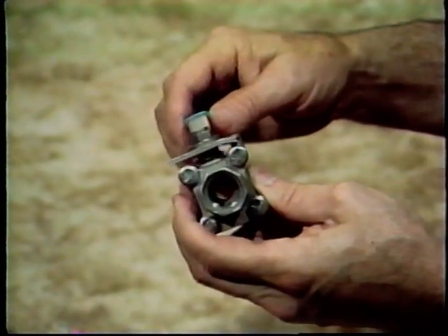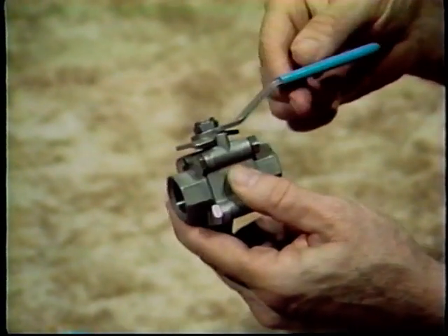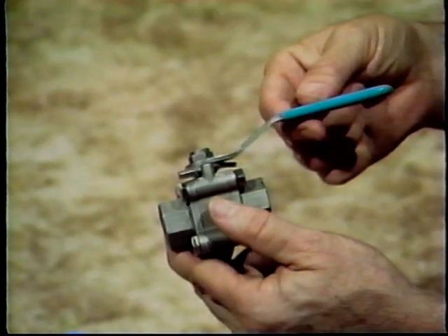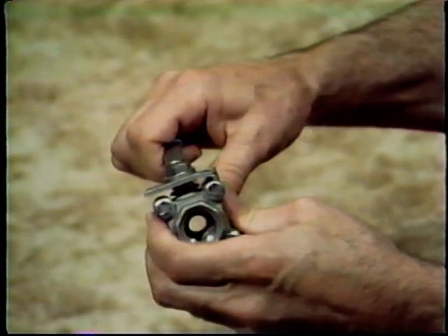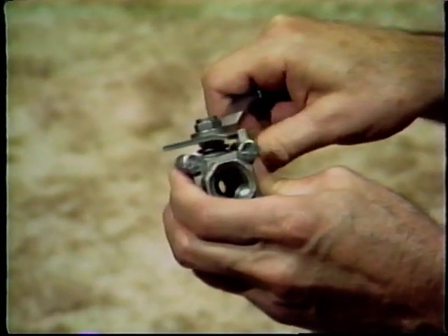For most pneumatic applications, however, the system normally requires a flow control valve with some sort of adjustable orifice, so that flow can be increased or decreased to meet the special needs of the circuit. And there are several types of adjustable flow control valves available. A common adjustable flow control device is a ball valve, like this one. By rotating the ball with this handle, the opening can be varied, which in turn varies the flow.